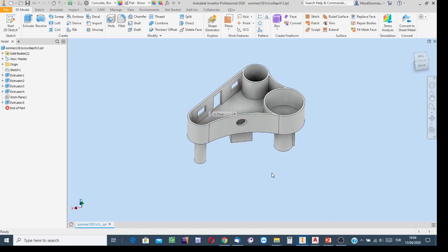In the second exercise, I used this work plane, with the sketch over it, and applying the extrusion process I created that empty space. Its axis is perpendicular to the work plane, to the sketch plane. Don't forget, the extrusion process is applied in the direction perpendicular to the plane of the sketch.